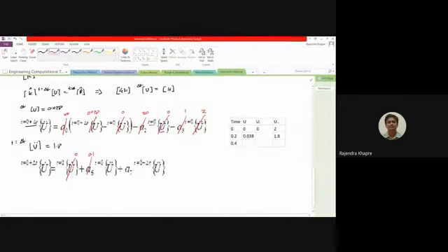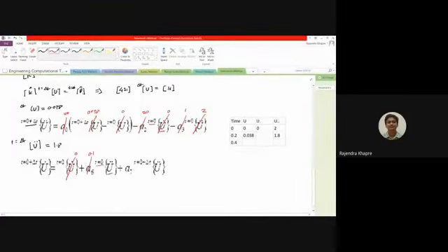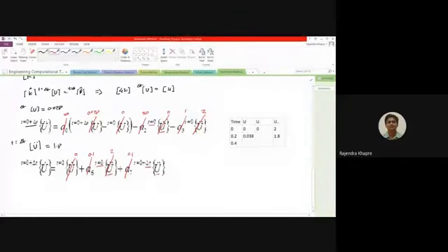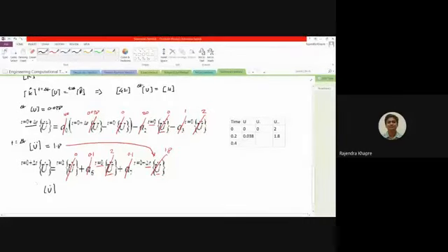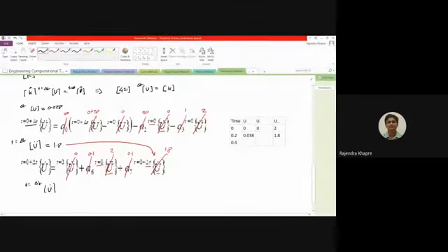Now here you see this is the acceleration at t is equal to 0, which is 2. Then this is a7. a7 is the integration constant, its value is 1. Now here this is the acceleration at t is equal to delta t, which we have already calculated. If you don't calculate the acceleration first, you won't be able to get the velocity. So this value is now 1.8. So ultimately you are going to get the velocity at t is equal to delta t. How much is this?